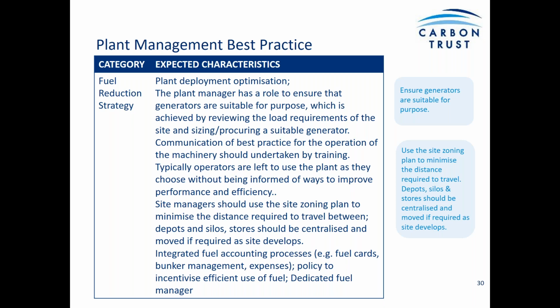Very often you go to whoever you hire the generator from, and they'll usually give you the one that they have available, whether it's appropriately sized or not. If it's oversized, then it's obviously going to use more fuel than was necessary. So you need to try and get a handle on what the initial site loading is going to be to help you better specify that as well.